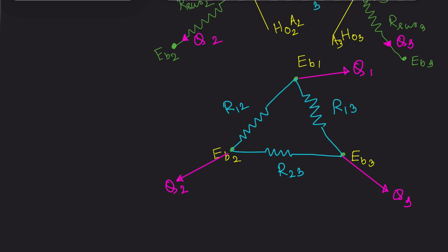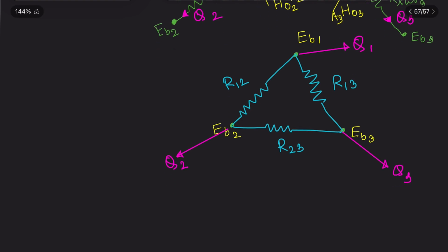Okay, you can also draw an inward arrow indicating that the net radiation heat transfer is inwards to the surface. That will not alter your answer. If the actual radiation heat transfer is outward from the surface, then you will get the answer as a negative number. And the irradiations will be something like this. Now, irradiation you cannot show by an outward vector, because irradiation by definition is actually falling on the surface.